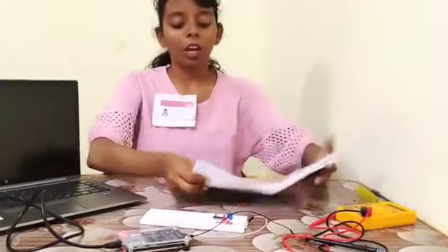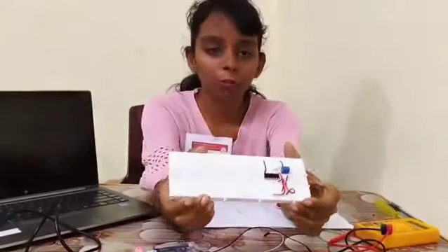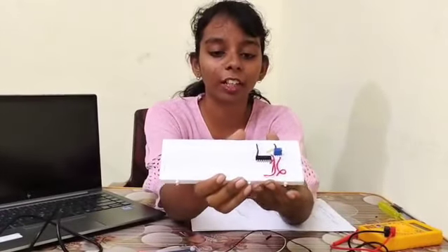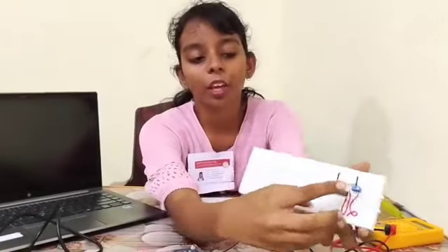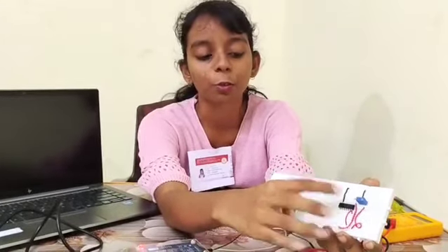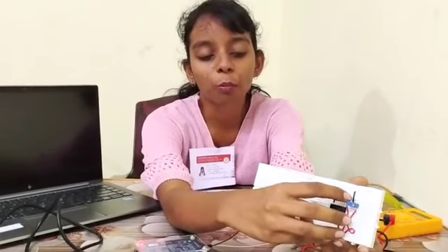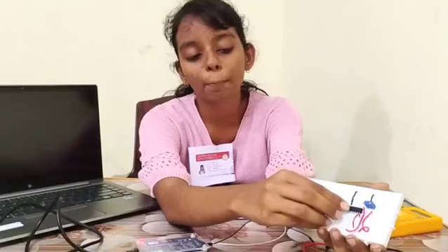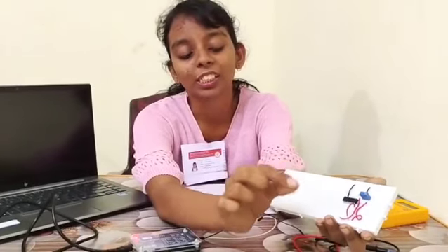And now, I have constructed the circuit which matches the circuit diagram exactly. Here, the trim pot is directly connected to the IC 7400. Pin 2 of the trim pot is connected to pin 2 of the IC 7400. Pin 7 of the IC is connected to the ground, and so is pin 3 of the trim pot. Pin 1 of the trim pot and pin 14 of the IC are connected to the input voltage source strip, also called the VCC strip.